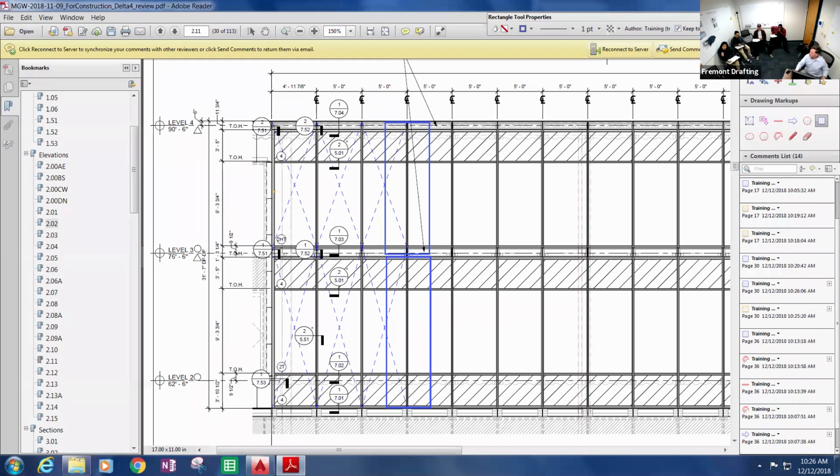Just while you're on that, maybe could you go over those symbols that are right there on that elevation? Sure, because that'll kind of tie into that. It's indicated on the drawing. The symbols we use for our dead load and wind load: we have a triangle that used to be filled in. Looks like it's hollow now. Maybe it's a rivet thing. So we use triangles for dead loads and circles for wind loads. That's why you can see at level 3 you have both symbols, because it's taking both dead load and wind load. It also shows, and this helps me understand too, the X's of the units. Each unit needs a dead load and a wind load.